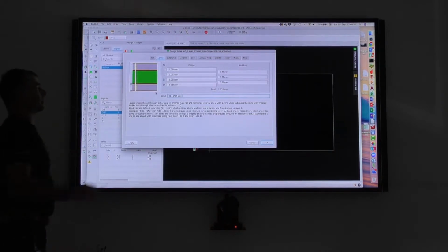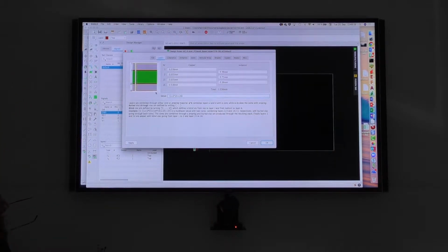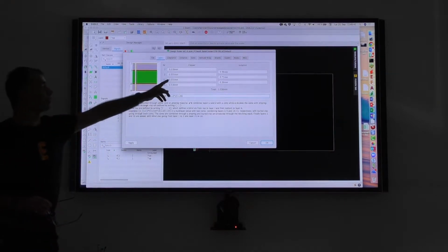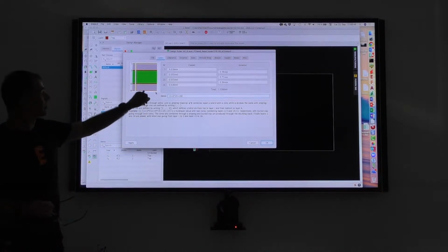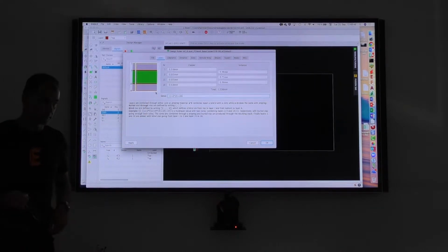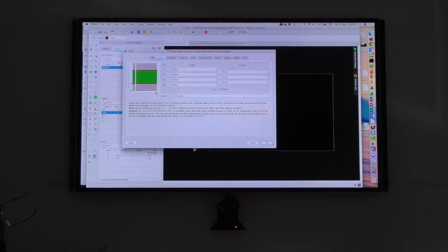There are certain thickness values for the board. Inside we have copper foil, which has 35 micrometers, and there we have 18 micrometers, which is, how is it? Let me think. It's quite 1 ounce.